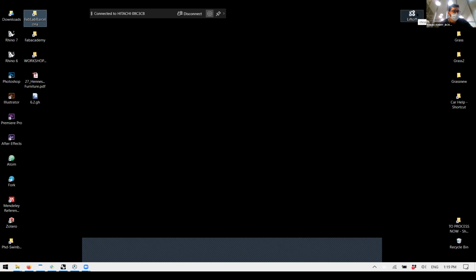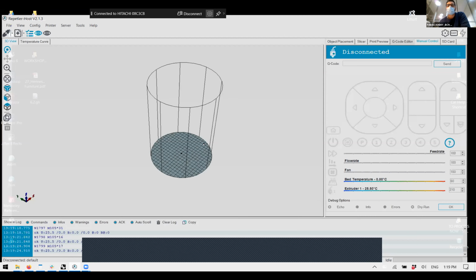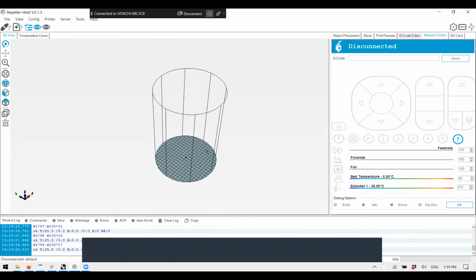Okay. So guys, connect to the machine. Let's go over the configuration of Repetier. We need to configure a few things. Basically, it's about the machine that we are connecting: whether it is Delta or Cartesian, and the protocol that communicates. Luckily, most of the printers connect the same way. Someone connects to that printer, and someone connects to this printer, please.